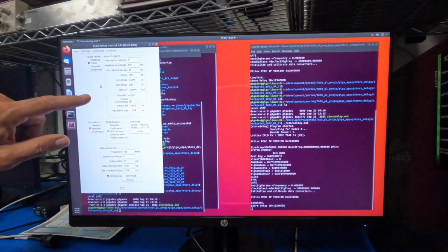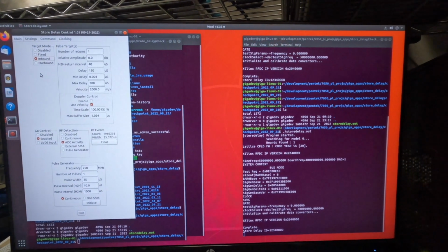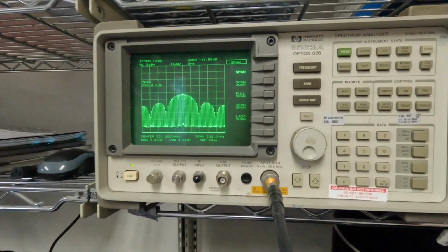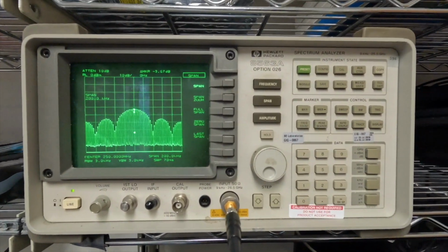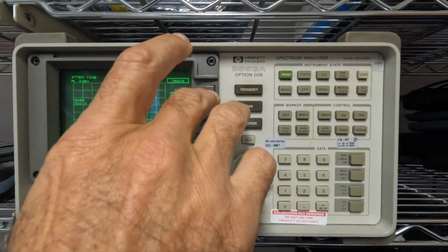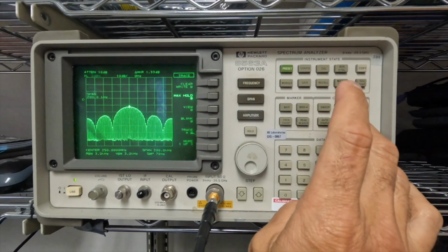And we're going to go back to a high velocity inbound motion, and we're going to look at our spectrum analyzer because right now we don't have a Doppler enabled. So let's put a marker of what a 0 Doppler offset looks like.